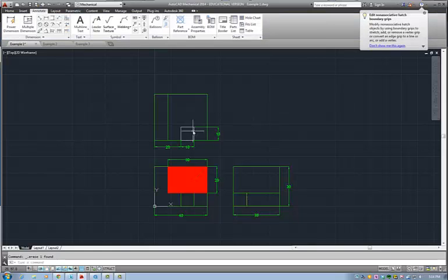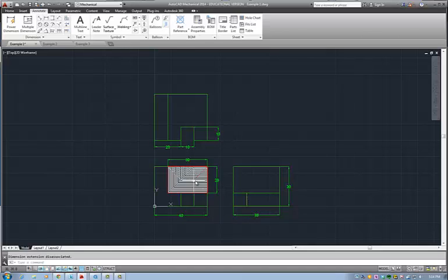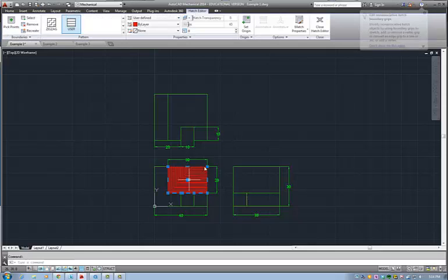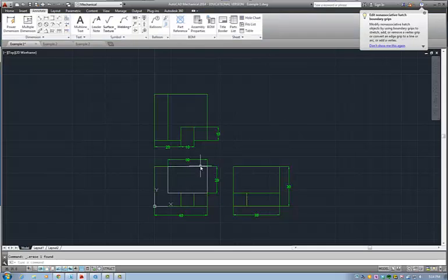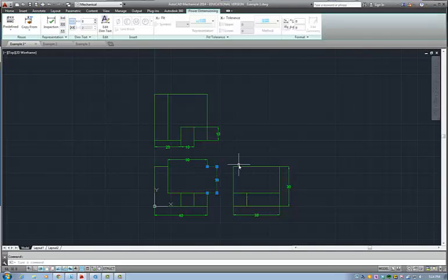So to dimension this missing part here, I will actually just need these two, 10 and 10, which tell me the size of this square, and 20 is for the location. And for this other one, 30 and 20 are the size and I don't need location because this one is in the corner. It shares the corner with the existing material. So I will delete the sketch and this is basically what you would like to see.